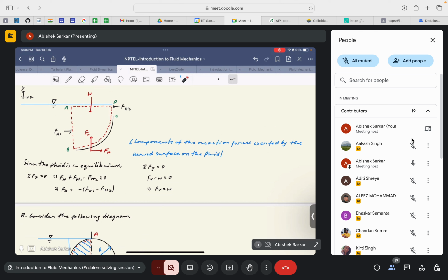as Professor Chakraborty might have mentioned, the horizontal force that acts on these surfaces would actually be the force that acts on the projection of these curved surfaces. So the projection of this curved surface here, BC, would be a rectangle. It's a particular sector of a circle. Let us say, for example, the simplified case, like this, and say the radius of this particular circle is r. Then the projected surface area of this curved surface would be r times L.